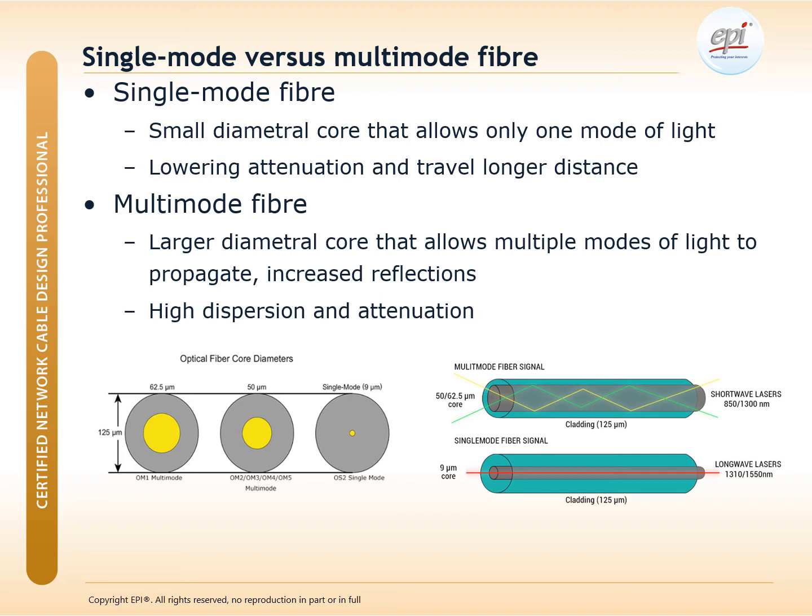For the multi-mode fiber, usually we use an LED light source or light transmitter, and the LED transmitter will come out with hundreds or even thousands of light rays, with diffusion, so a large amount of light going to different places. The multi-mode fiber has a bigger diameter to allow many different light paths to go through.